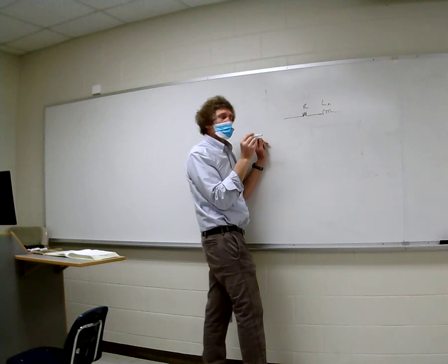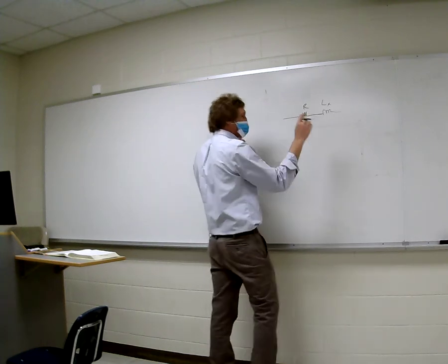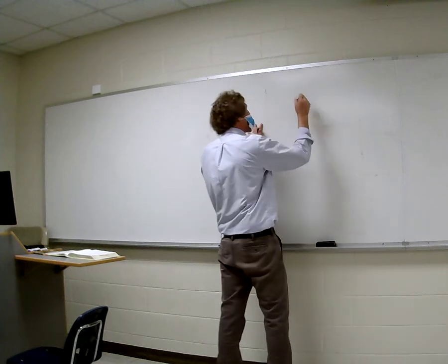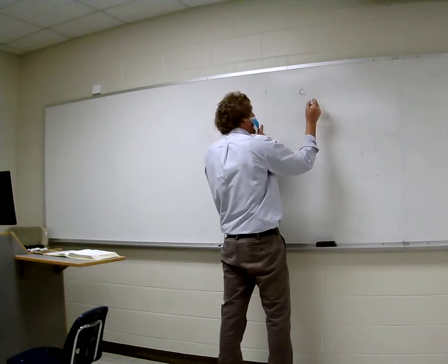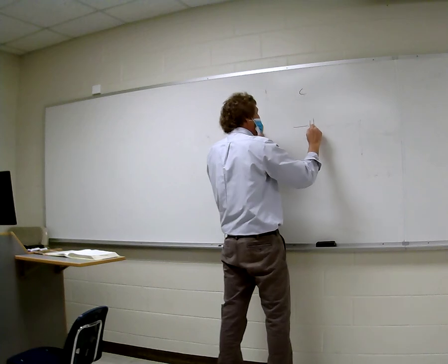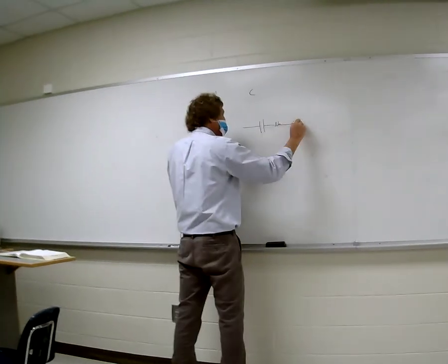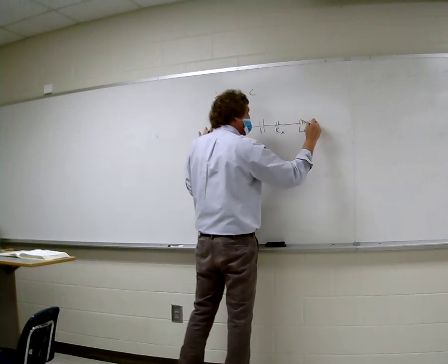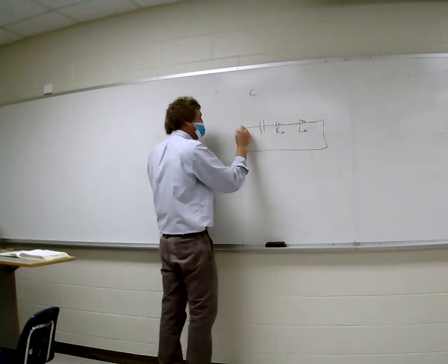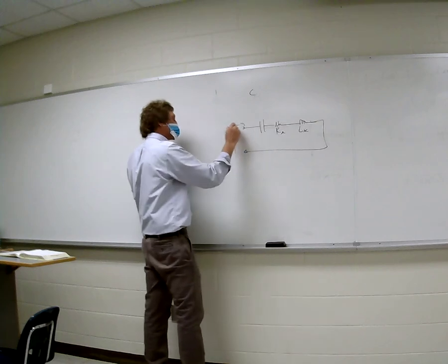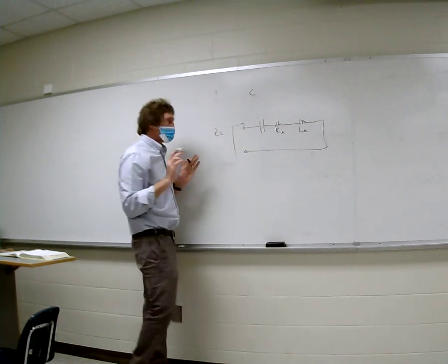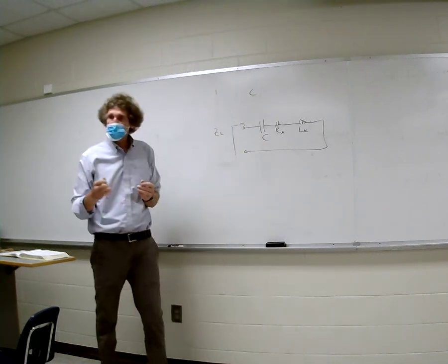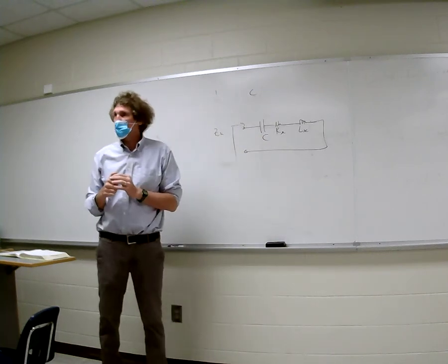And this is going to, actually, tell you what, let's do a capacitor now that I think about it, because that one's the one. This will be a capacitor. For C, we start out with a capacitor, then you have a resistance that's Rx, and you have an inductance that's Lx, a lead inductance, right? Are you with me? This would be the impedance, Z. Are you all with me on this class? We're just assuming this is a capacitor model, first order, correct, that I gave you?